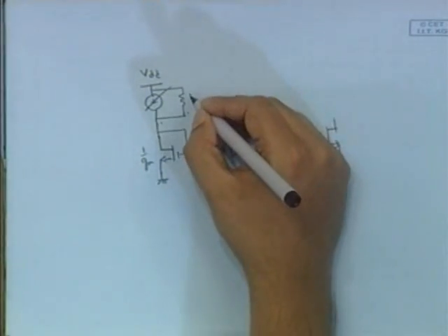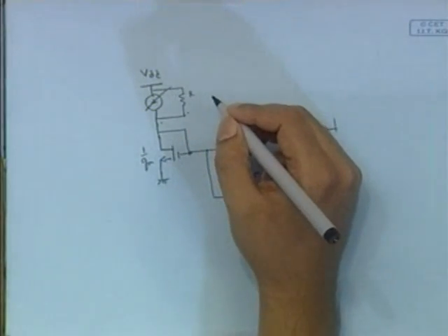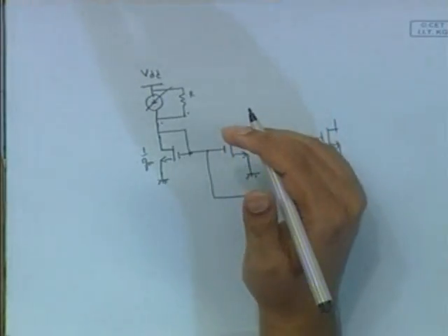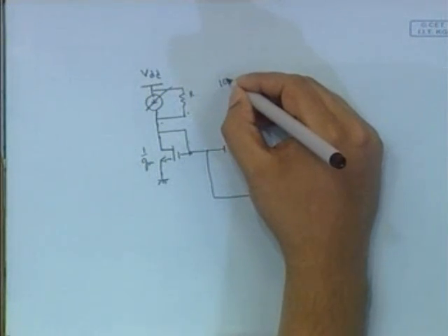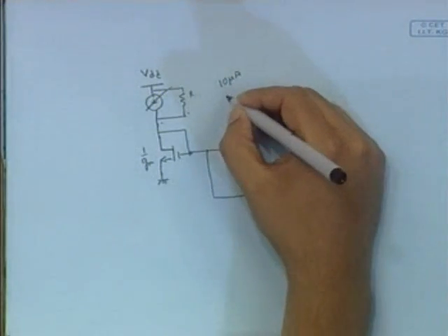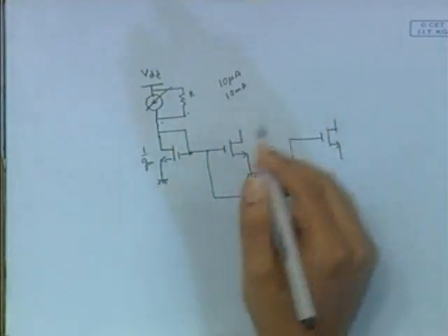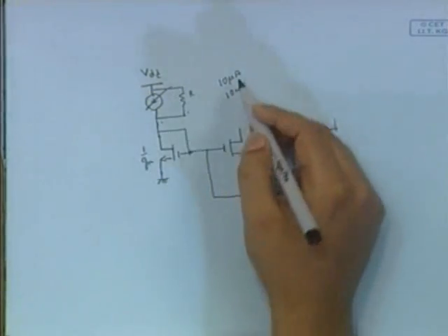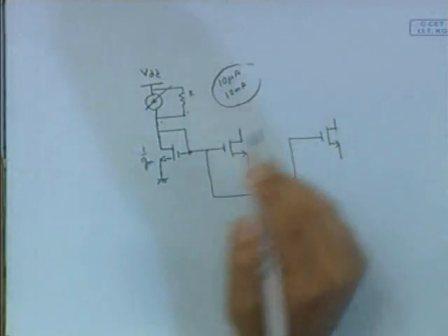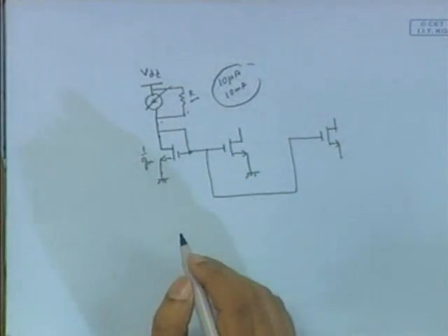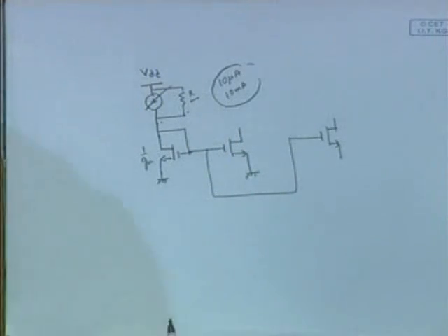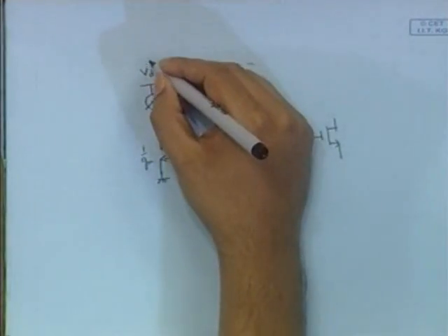Suppose for your design you have to design a current, in some cases 100 microampere, in some cases 10 milliampere. To support this amount of variation in current, there should be a large variation of this R. Again, this is very much dependent upon whatever supply voltage you are applying here.